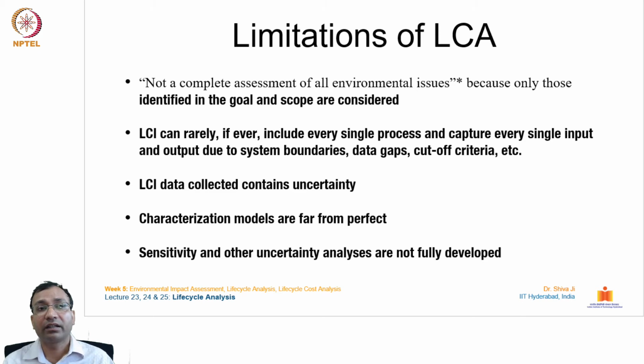LCA can rarely, if ever, include every single process and capture every single input and output, due to system boundaries, data gaps, and cutoff criteria. So there could be some limitations while undertaking the study itself: whether the system boundary is defined, whether all of the data is available, whether the data is available in a quantifiable format, because LCA analyzes only quantifiable data. If there is some data which is subjective in nature, that cannot be processed under LCA.